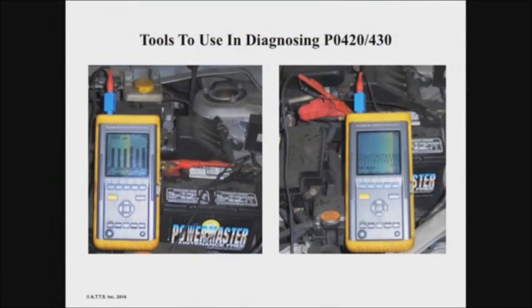Relative compression. This is very, very important because if you don't own a Ford IDS, how many guys have a Ford IDS in here? Oh, good. Toyota touchscreen. Well, you know you can do relative compression right from the tool. Toolbox on the IDS, piece of cake, probably the nicest tool out there.